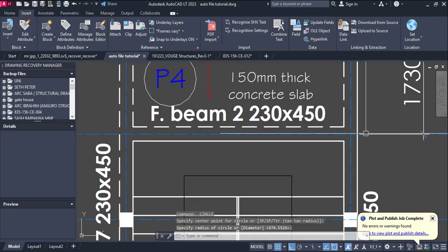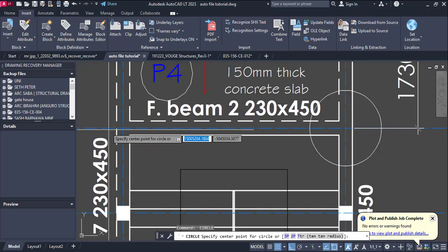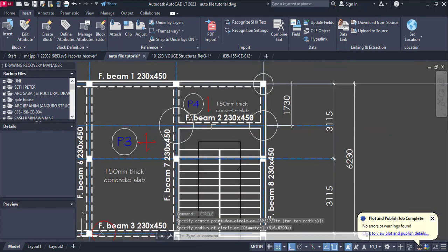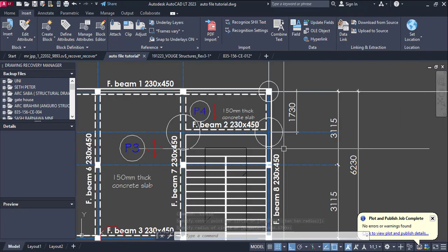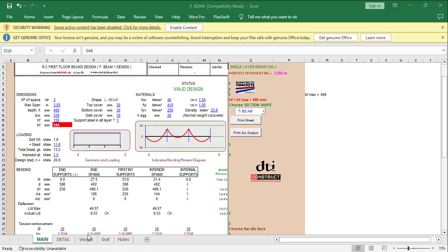But in the case of the other beam, if you circle this part and this part along the end support here, you realize that this is giving you a T shape. This is also a T shape, which makes that beam a T beam. But this particular beam is an L beam. So that's basically how to know if a beam is T or L. Because this beam is an L beam, from here you can see the shape is L beam.